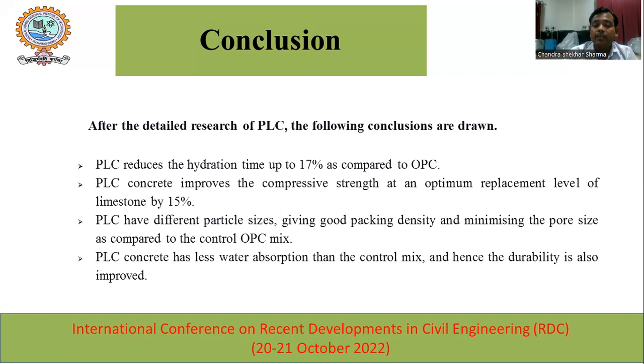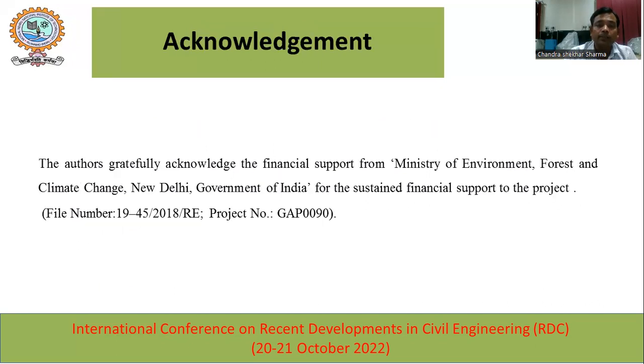PLC concrete has less water absorption and durability is also improved. PLC concrete improved the compressive strength at an optimum replacement level of limestone of 15%.